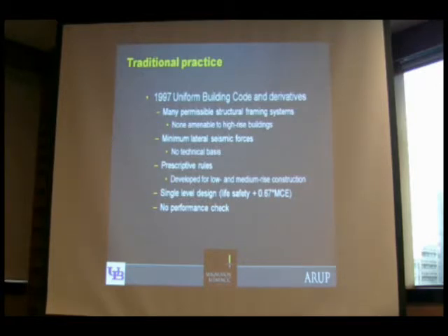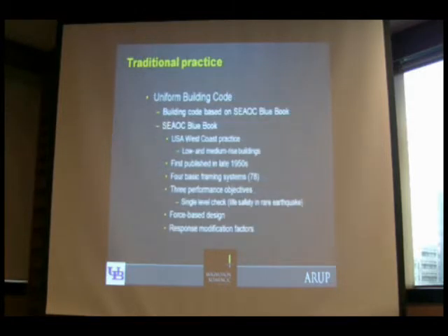In Australia, your design basis is a response spectrum with a 10% probability of exceedance in 50 years. We use something a little different in the United States, but they're not too dissimilar. And importantly, with our traditional practice, there is no performance check. You don't cycle back through the design at the end of the day to ensure that you're delivering the performance that's intended, in part because our procedures are sort of implied and not explicit.